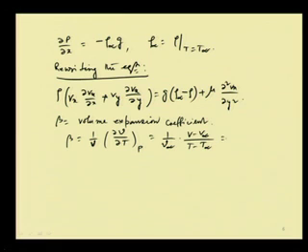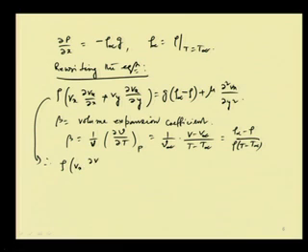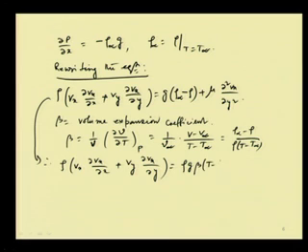In terms of rho, if we write volume as the inverse of the density, then we get it as (rho infinity minus rho) by rho into (T minus T infinity). So, we can write the previous equation as rho into Vx del Vx by del x plus Vy del Vx by del y equals rho g beta into (T minus T infinity), where rho infinity minus rho is replaced by beta into (T minus T infinity), plus mu into del square Vx by del y square.